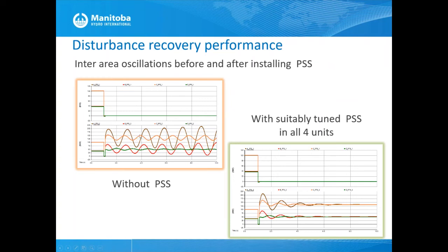The first peak divided by the second peak, and you take the log of that. I'm sorry, I have to correct myself. It is the log of the first peak divided by the second peak, and because you take the log of a number less than 1, in the case of negative damping, it will be a negative number.